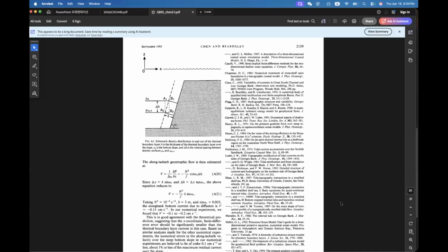But then we did not certify the converging solution. Like I showed you in the test, I make the resolution higher and higher, and the thermal boundary comes out. That's the converging solution. The one I showed you before is not converging. That's a numerical solution. You have to reach the true solution, so you need to do the convergence study.